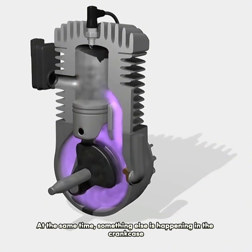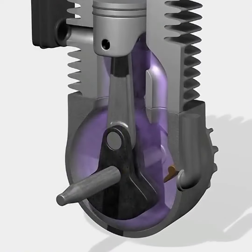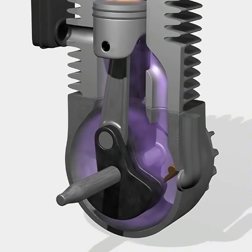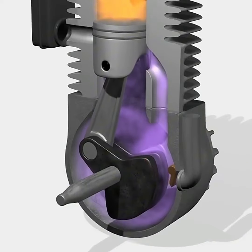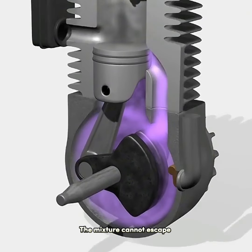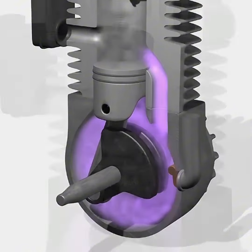At the same time, something else is happening in the crankcase. Back to the top. The piston is up again. There is also a gasoline-air mixture below the piston. This is pushed down by the piston. The resulting pressure closes the inlet valve. The volume below the piston continues to decrease. The mixture cannot escape and is compressed more and more.